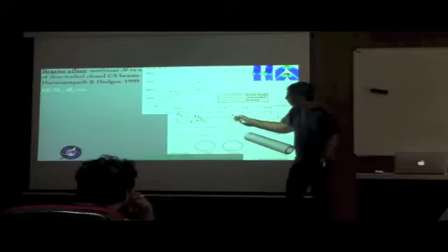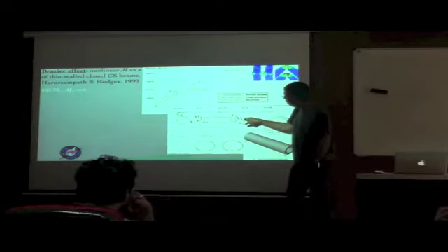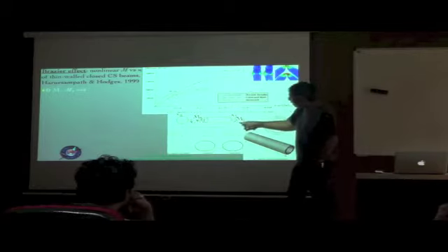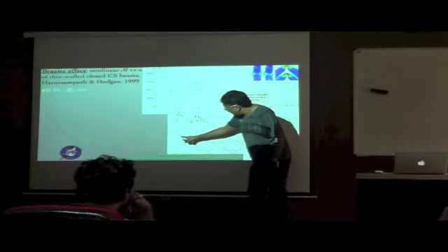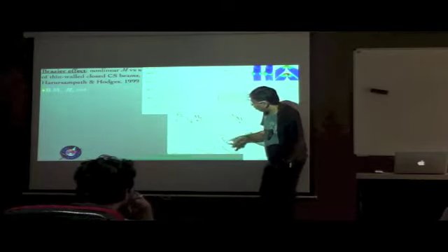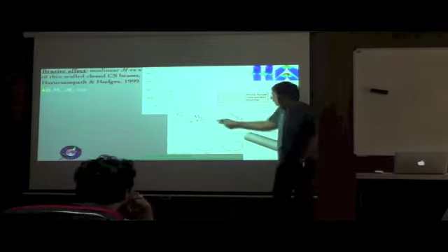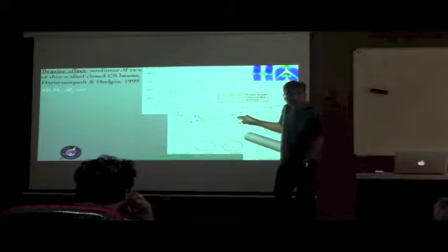Actually it's a load which anywhere inside happens to be the reactive resultant, the bending moment. So that's equal to M2, and that's about the x2 direction over here. When there is no load, you have a circular cross section. There is no initial curvature; this is a straight prismatic circular cross section beam.